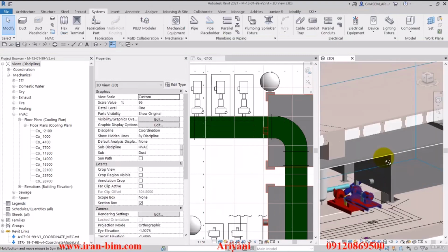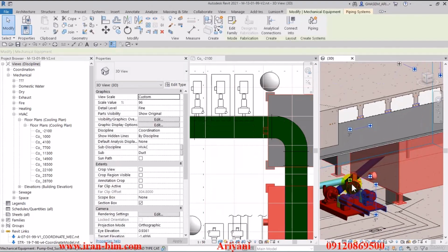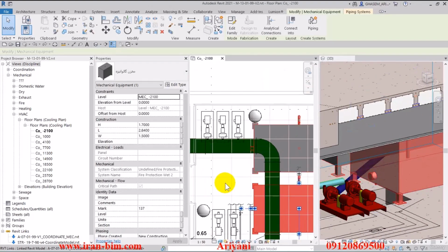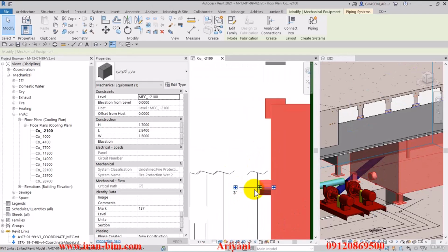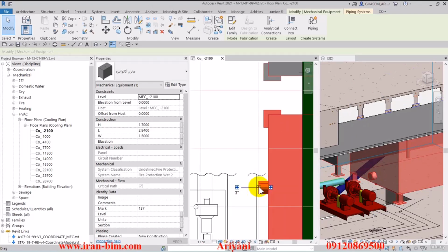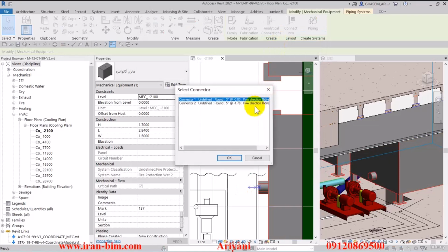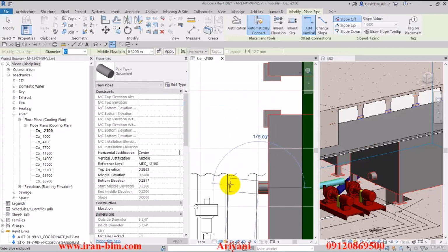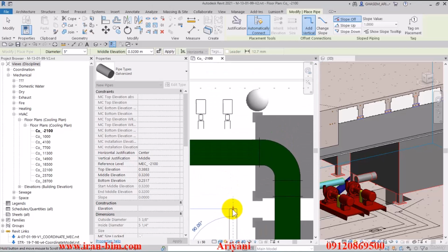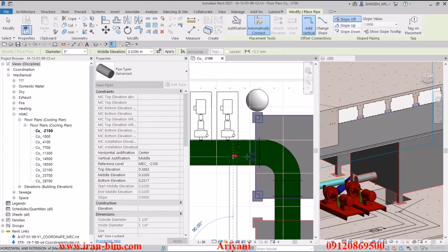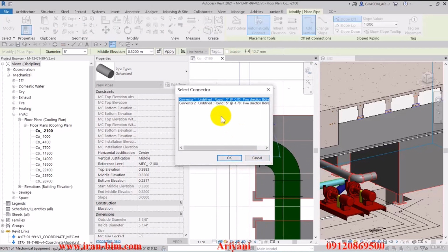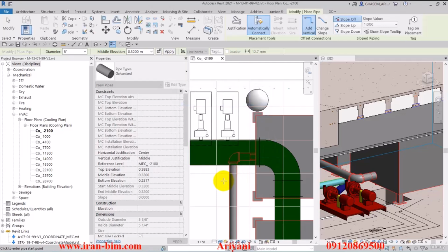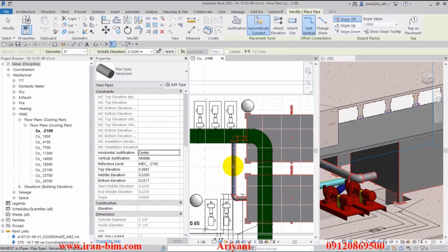So after that, we'll go over here and select the 5-inch pipe that we have right here. Right click on it and select draw pipe. And because we have the fire and the water together, it gives us a message. So here I can choose the 5-inch pipe instead and then hit OK. Then we continue the pipe up to this point and then it goes up here and then into the right. Now once again we'll select the 5-inch to connect this to.